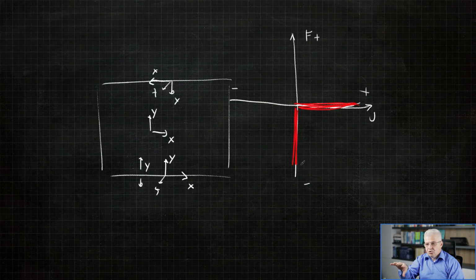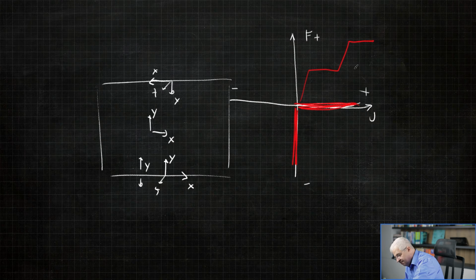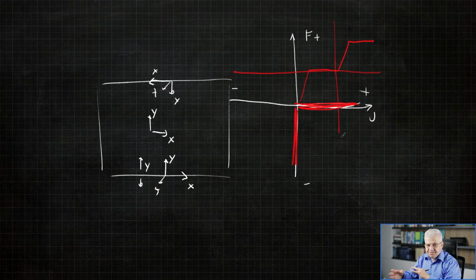You can really draw a polygon line if you want to create some sophisticated nonlinear hinges. There is only one thing you have to remember. It's forbidden to use horizontal and vertical lines, because for the convergence of these nonlinear models, you need to introduce some small inclination.